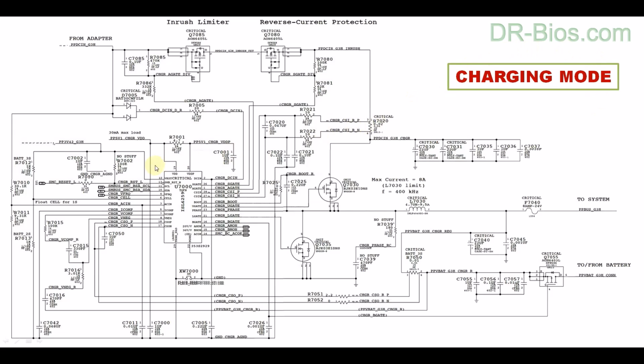As you see, the battery is healthy, and it is connected to the device, and PP3V42_G3H voltage is present, and SMC_reset_L signal is present on the IC, and the IC is on standby mode, and the reference voltage PPBUS_G3H is being provided through battery.